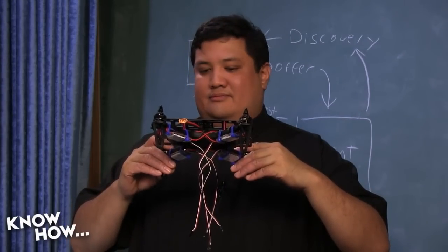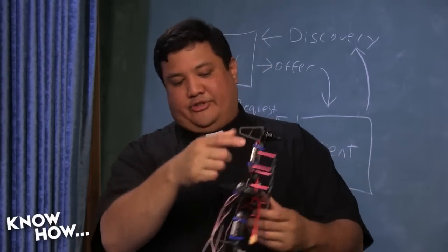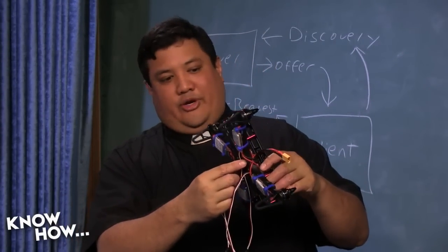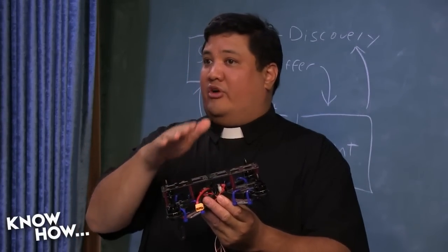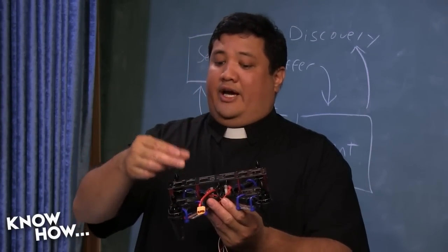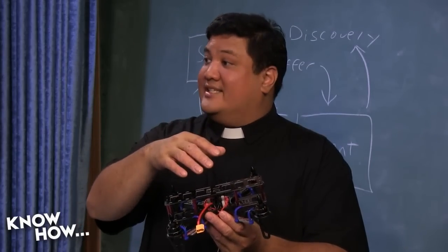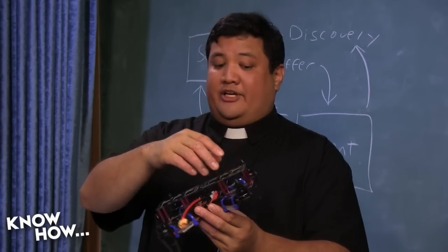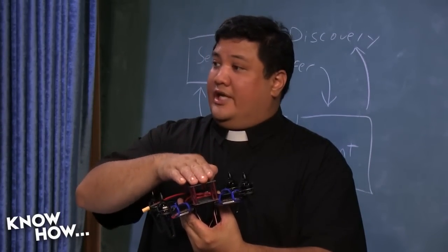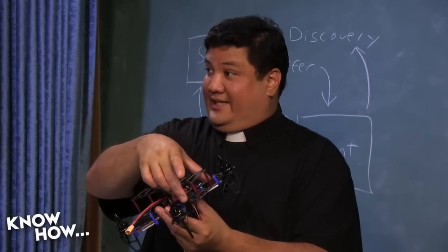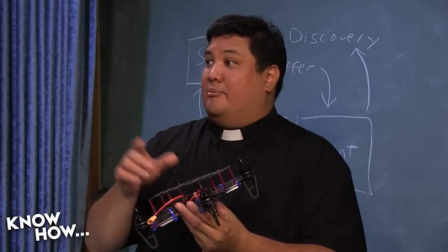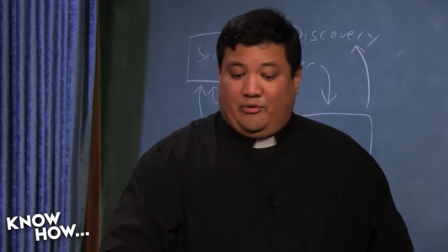Where are you going to hide the battery on that? The battery on this actually goes right down in the middle. Hanging on the bottom? Yeah. Straight down in the middle. Or some people will actually put it up at the top, but I want to reserve the top for all the antennas I'm going to have. So there's going to be an FPV antenna, a GPS antenna, and then probably an FPV camera in addition to the GoPro. So I want to protect the GoPro inside the cage, and I'll put an FPV camera on top, because what I want to do is I want to use this.